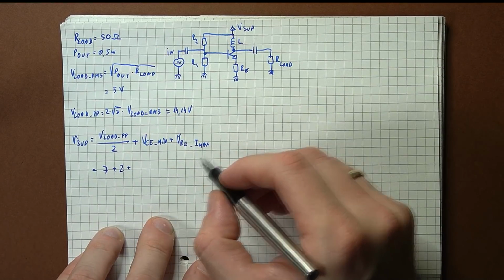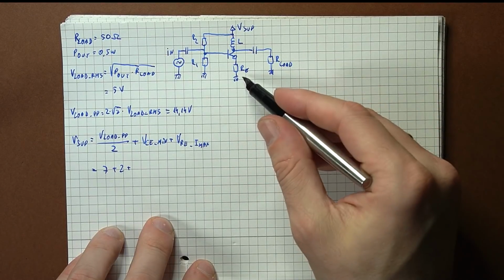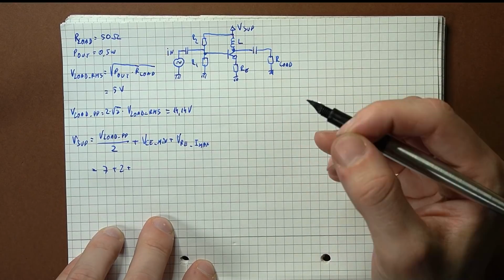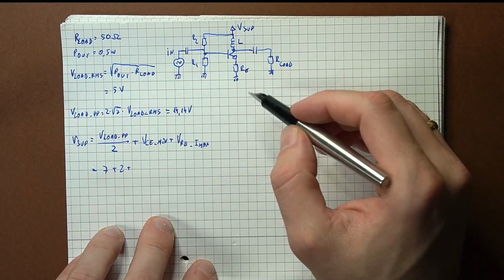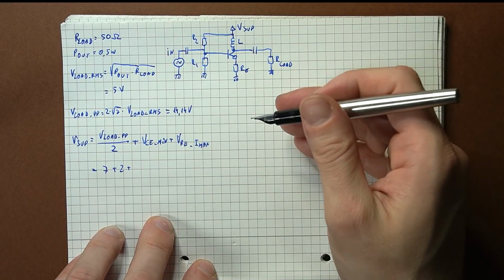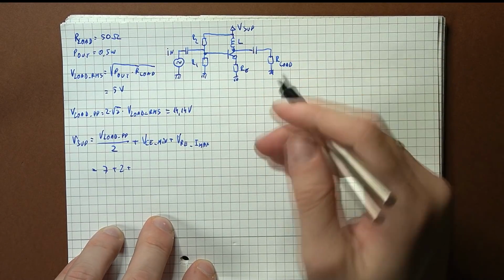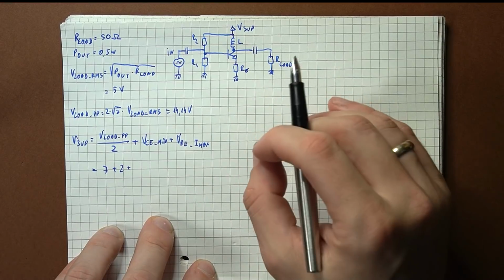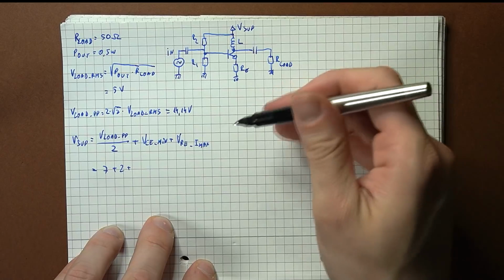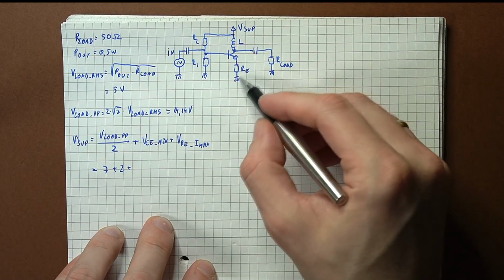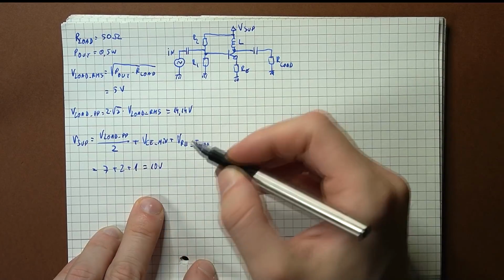And for the emitter resistor, well, this component has two purposes. On the one side, based on this component and the load value, we can set the voltage gain of the circuit. But secondly, the larger the voltage drop that occurs on this resistor, the more heat gets dissipated, but also the exact base emitter voltage, which is temperature dependent, becomes less important in analyzing the stability of the circuit. So by having large emitter resistor voltages, we can make the circuit more stable. So we'll set this voltage drop to 1 volt. So the total supply voltage will end up being 10 volts.